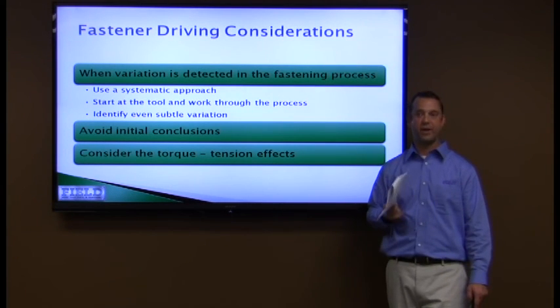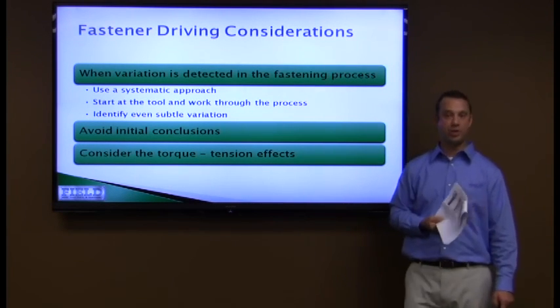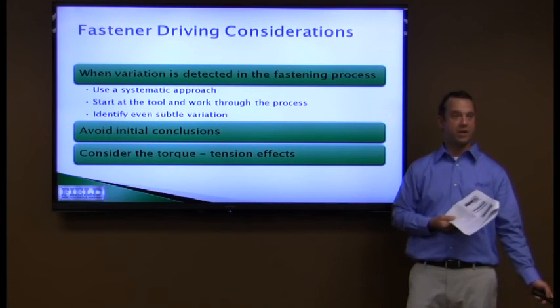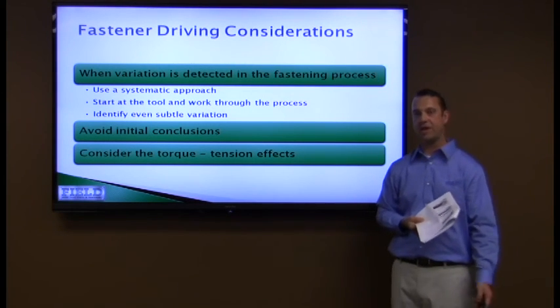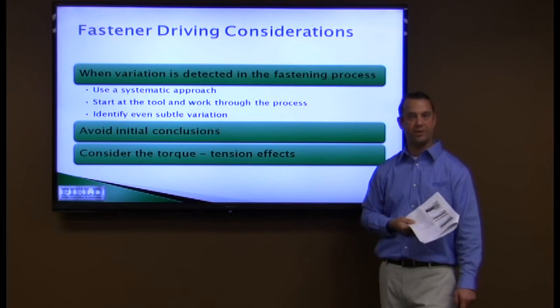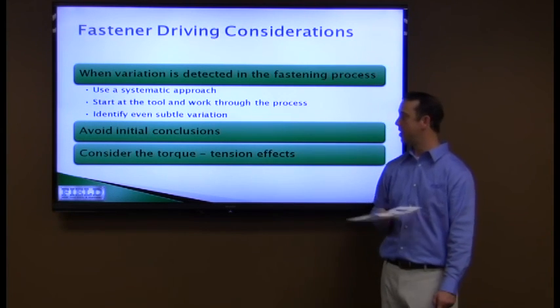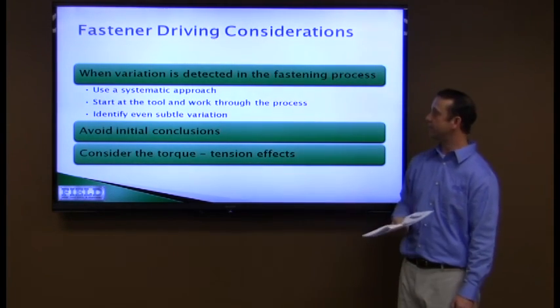Like we mentioned, did something change recently? Did somebody switch out the fastener for something else they had in stock? Did they change the plating to get better corrosion resistance and not change your torque number? So consider the torque tension effects.